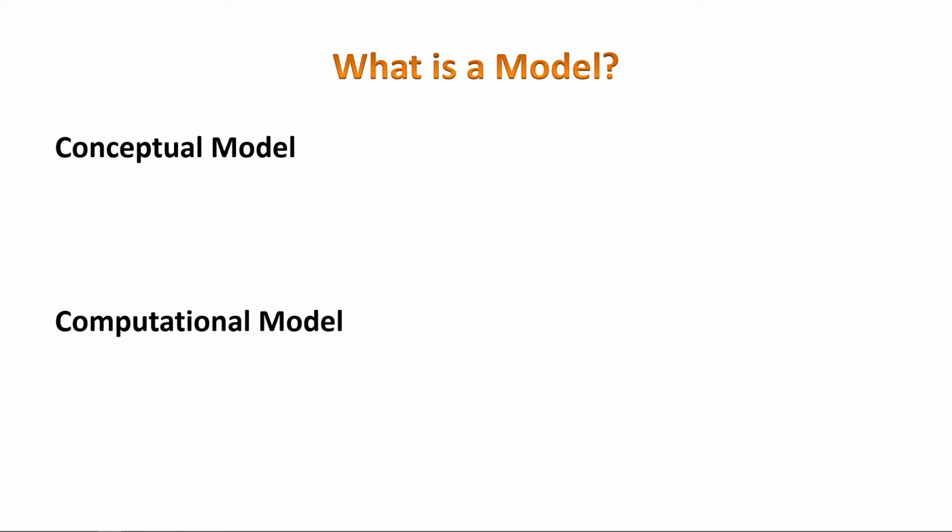On the other hand, a numerical model is the mathematical representation of your conceptual model. So now I have a conceptual model. When I represent it mathematically and then I solve it numerically, then this is a numerical model. So basically, it divides your groundwater system into interconnected cells and solves the equations that describe, for example, flow or contaminant transport or whatever. Let me show you.